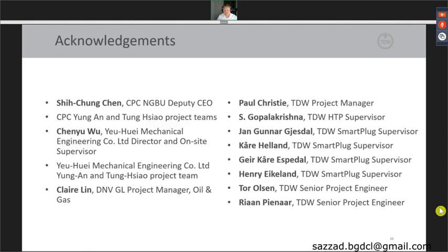Mr. Arif Laksana has a question. Was the smart plug applicable for flexible pipes with carcass material inner side? I can answer that. To date we have not isolated in flexible pipe. It has been considered in the past, and we are currently in early stages of discussion with flexible pipe manufacturers because of the improvements in the stress capabilities of flexible pipes, to see whether it is a feasible option. But to date, we have not done that yet.